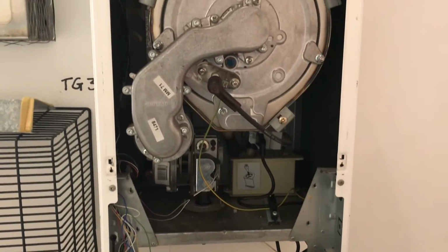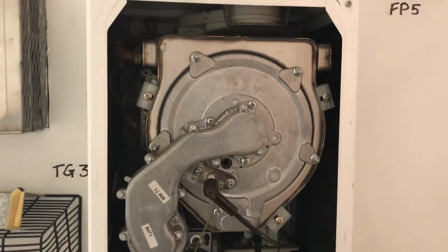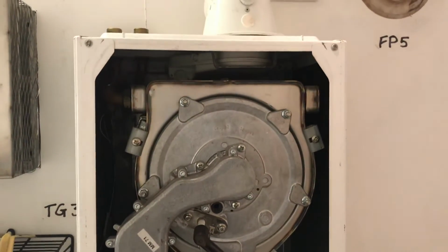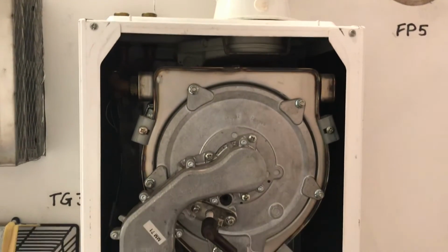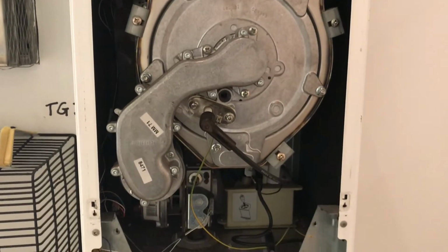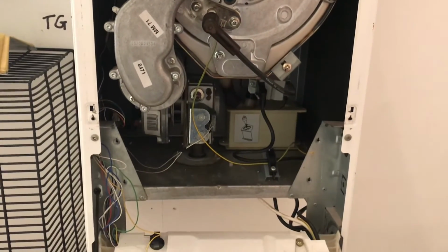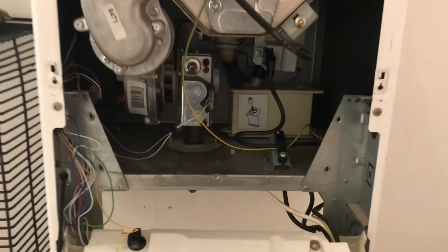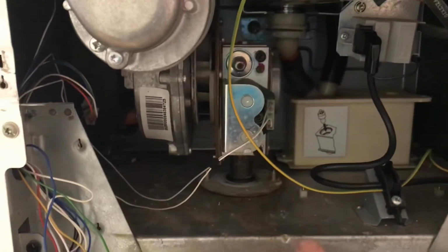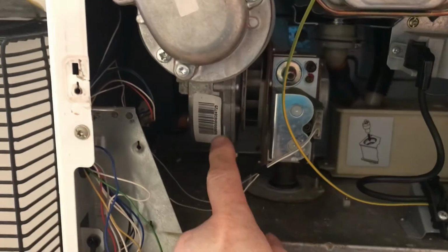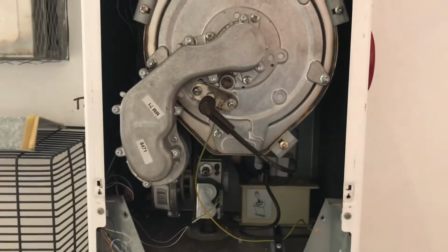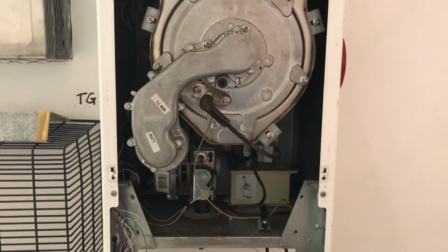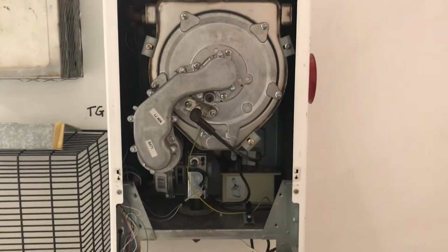Now this boiler we're looking at is what we call a heat only boiler. It's a condensing boiler, but a heat only. Unlike the system boiler we've just seen, it has no pump and it has no expansion vessel. They would all be installed externally from this boiler. So basically all it has is the gas valve, which is here, a fan, which is here, and the burner, which is here. Again, condensing, again up to date. You can still buy this boiler, but this is a heat only boiler.